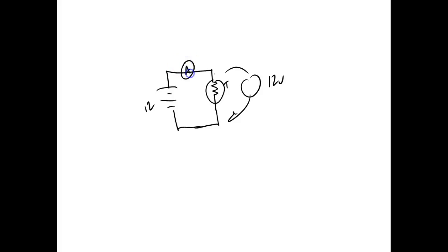The only other option we got is to use an ammeter. Ammeters we don't use that much. Well, normally what we do is we put a fixed resistor that I know the size of, and then I put the thermistor in series with it. Now I've got 12 volts. This 12 volts is going to be distributed across the two resistors, right?